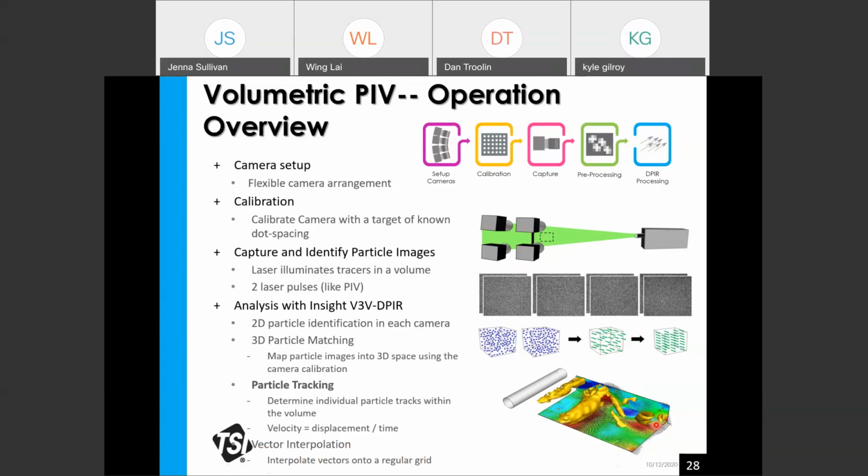So this is a result, again, of the vortex shedding of the cylinders. If you remember, using the planar PIV systems we are able to see some information of the vortex shedding, but using the volumetric system, we actually can see the entire vorticity field generated by these particular cylinders. So the information is much more complete. And again, using the high-speed system, we are able to see essentially the change of the flow with respect to time as well.